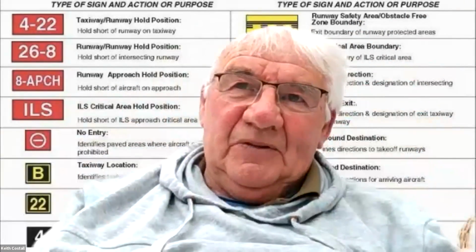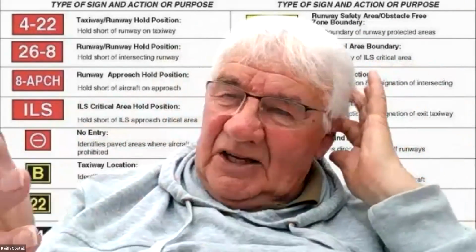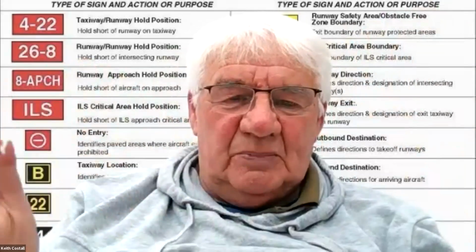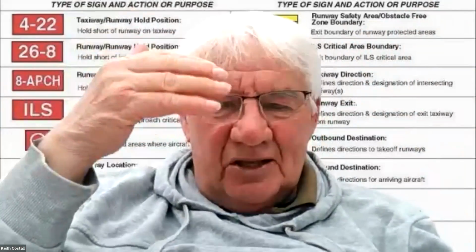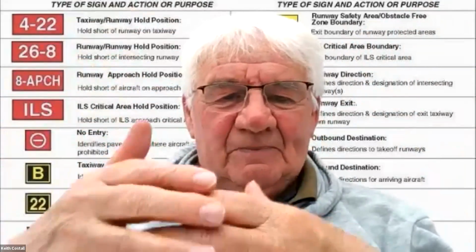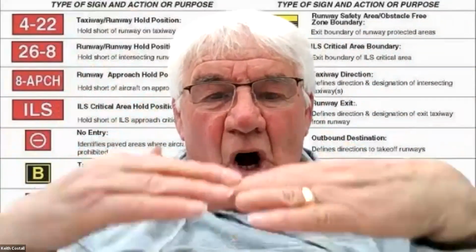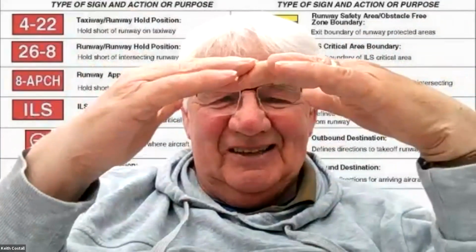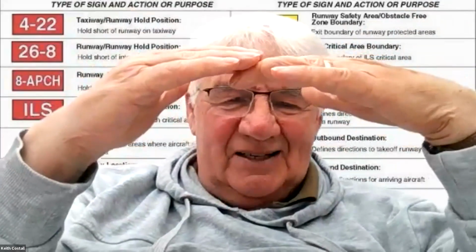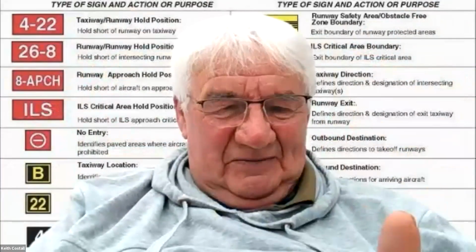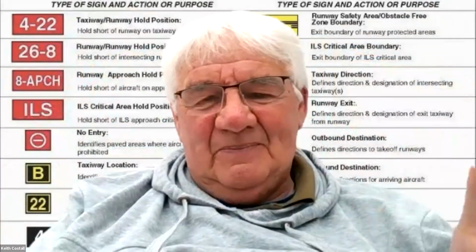So if we go to, for example, runway related lights, which is 5 steps as the basic 5 steps, where ICAO call for 30%, they say 100%, 30%, etc. That's based upon the top tolerance of the current, where if we look at the bottom tolerance of the current, that's only 20% of light output for step 4,